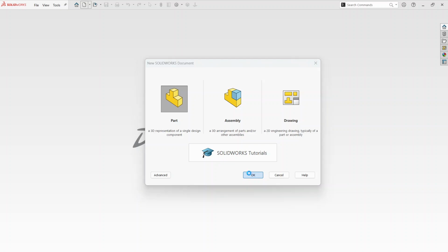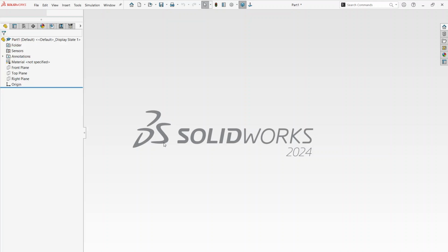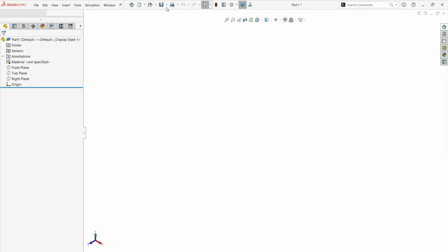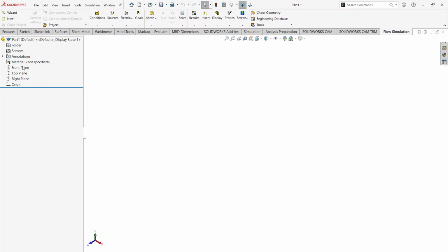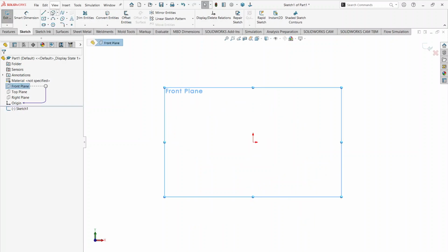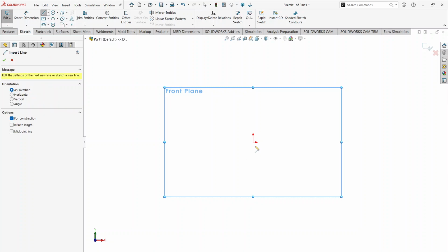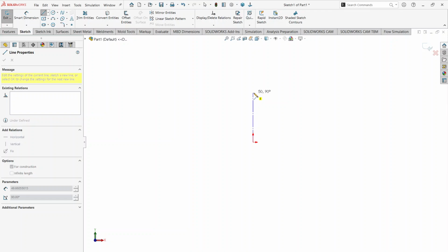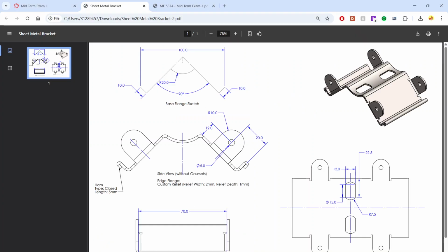and we are going to select the plane and start a sketch there. So I would start from front plane and create a sketch there. Go to center line and create a vertical center line, which would be my axis for mirroring later down the road. So the sketch showing that here, I can create an arc.